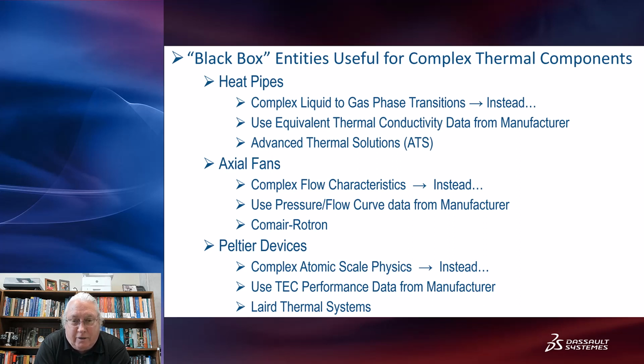And so these axial fans, you've got these blades and the geometry, and if you want to do a simulation for an actual fan, you have some kind of rotating volume to simulate the blade spinning around. And that's so complex, we don't want to deal with that. The only person that would do something like that would be the manufacturer of the fan. Instead of that, we're going to use the flow curves from the manufacturer. They publish those data sheets with their products, and we can input those pressure flow curves right into SolidWorks simulation, and it will simulate the operational range of the fans themselves.